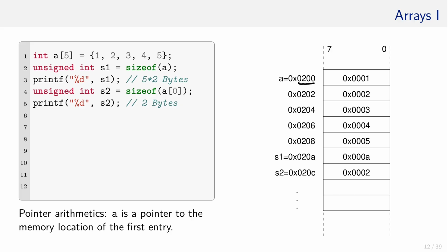Well, remember that an integer is 2 bytes in total, and this memory stores 1 byte per address as indicated by the LSB of 0 and the MSB of 7. Hence, the memory's so-called word size is 1 byte. That means storing an integer requires 2 memory locations.